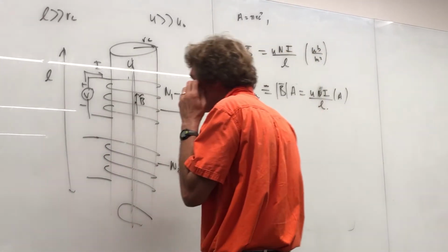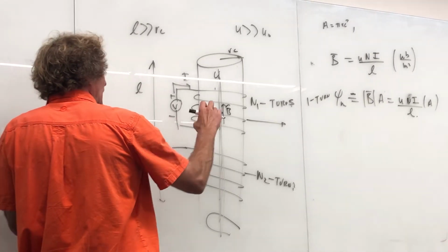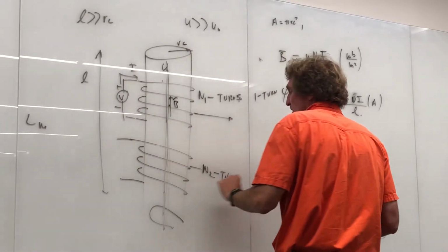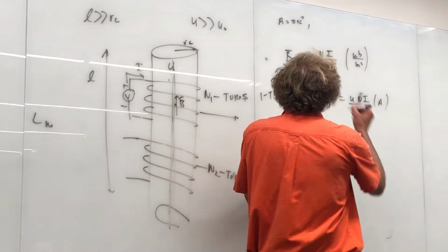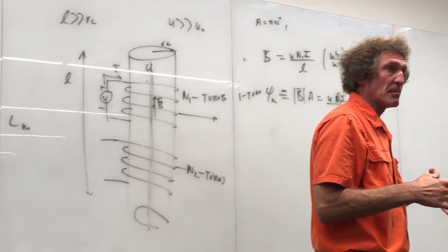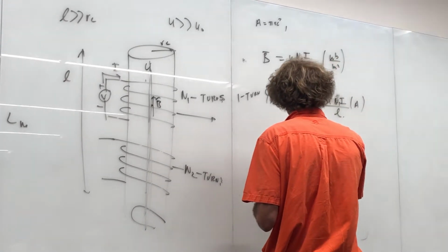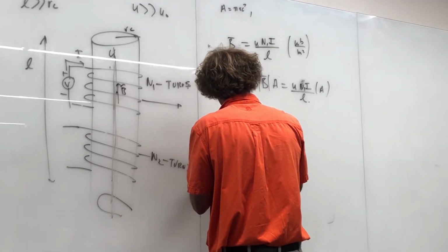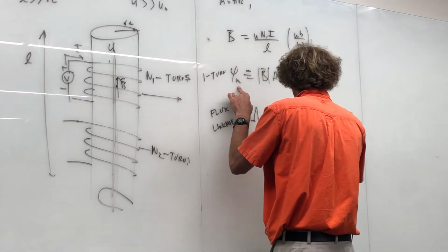Now, if I'm looking for the mutual inductance between these, Lm, what is the mutual inductance between this circuit and this circuit? Then I find the amount of flux that penetrates N2 turns, right? Are you with me? And this should be N1 here. That is the amount of flux that's penetrating any one turn. But the amount of flux that penetrates this secondary circuit where I have N2 turns would be equal to this times N2, and this is the flux linkage, by the way.